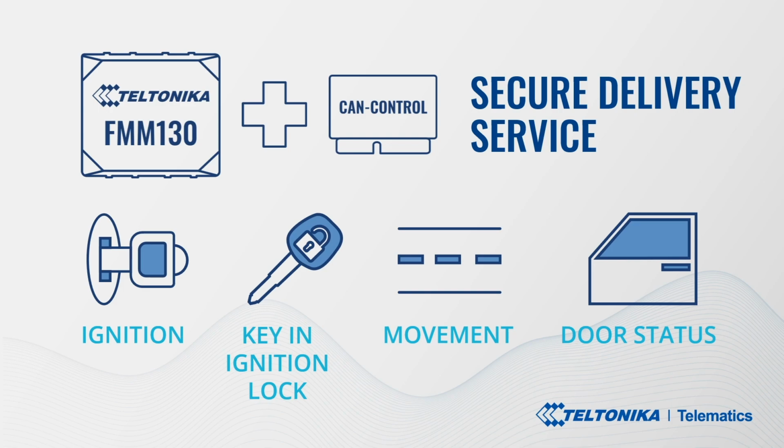Our solution with state security flags informs that ignition is on, key is inserted, the accelerometer shows that the vehicle is not moving, and from door status we get information on door events when they were opened or closed. When the driver closed the door, the server got the event status that all doors of the vehicle are closed, and it is configured to send a command in 15 seconds to the central lock control to lock all the vehicle doors, and all parcels are secured in the vehicle.